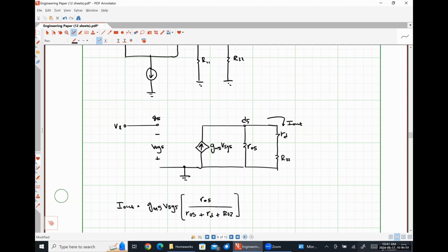Or I'm using the fact that I have two resistances in parallel and I'm using the current through the branch I don't want over the sum of the branches, instead of doing the reciprocal, just because that's going to be gross and messy. It's going to wind up giving us the same result. Okay? That is literally the exact question I was about to ask, but yes.